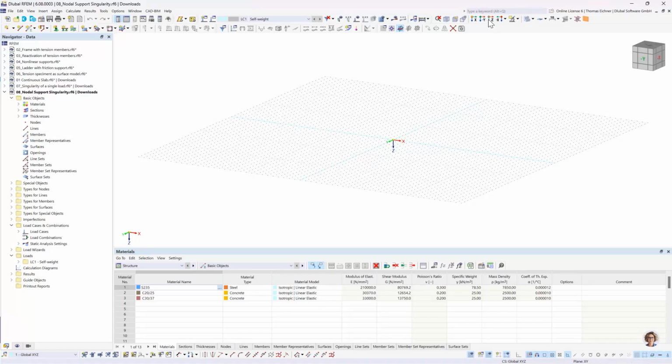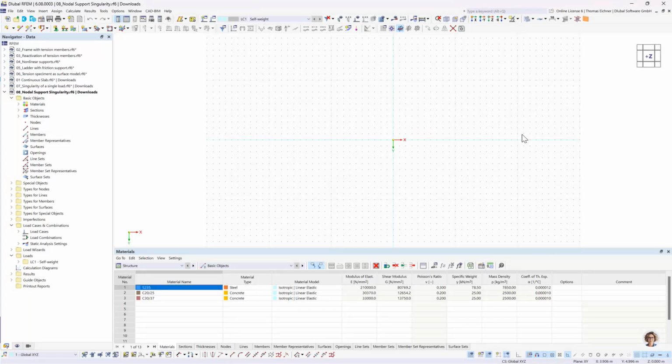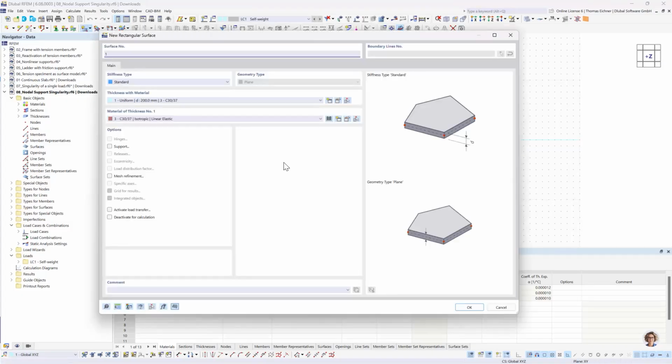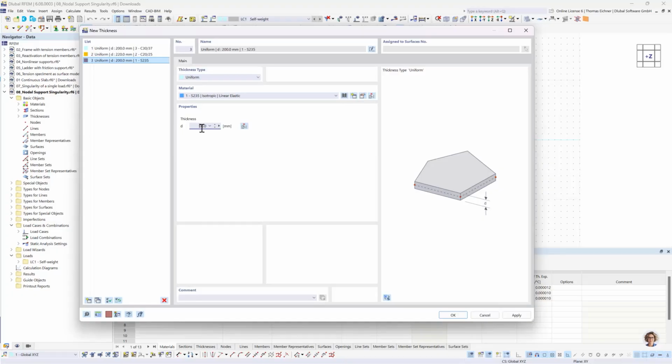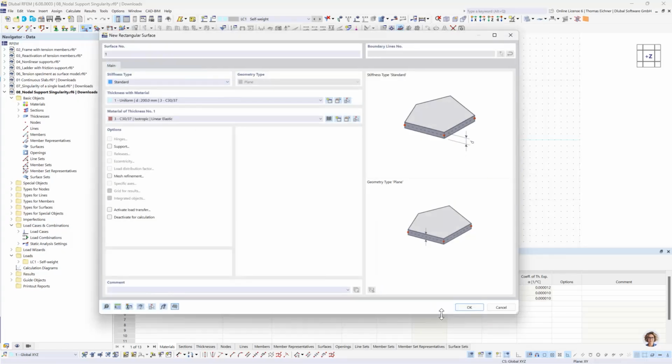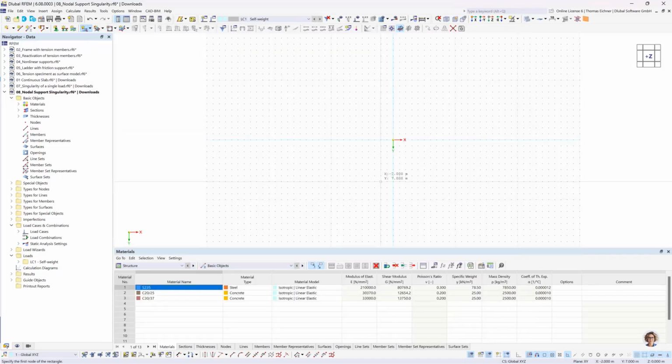And there it is. Again, we're gonna go for 4 slabs here. Let's just start right away. This time it's quite easy. The only thing I wanna change is here. I wanna go for 300 millimeters again, and stay with this C30/37. Press OK. And then we can create our system with, let's say, 8 times 4 meters.